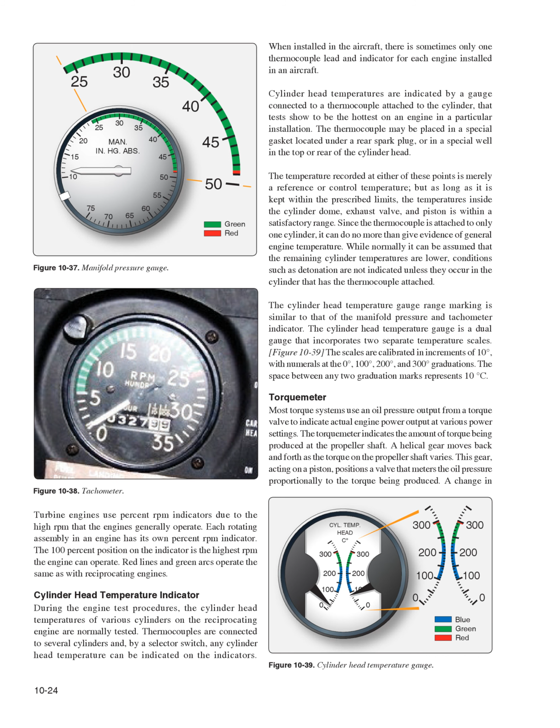The thermocouple may be placed in a special gasket located under a rear spark plug, or in a special well in the top or rear of the cylinder head. The temperature recorded at either of these points is merely a reference or control temperature, but as long as it is kept within the prescribed limits, the temperatures inside the cylinder dome, exhaust valve, and piston are within a satisfactory range. Since the thermocouple is attached to only one cylinder, it can do no more than give evidence of general engine temperature. While normally it can be assumed that the remaining cylinder temperatures are lower, conditions such as detonation are not indicated unless they occur in the cylinder that has the thermocouple attached.